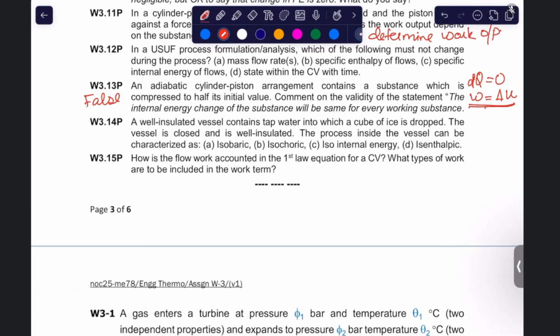But if it is very much sealed and rigid, then pressure could vary slightly because of the heat exchange that is happening between ice and water. There will be a melting of ice, so a volume change will happen, because ice has a different density than water. Because of that density change, a volume change will happen, so the pressure will be varying. So we cannot definitely label it isobaric unless we know the vessel is a bit flexible or rigid.